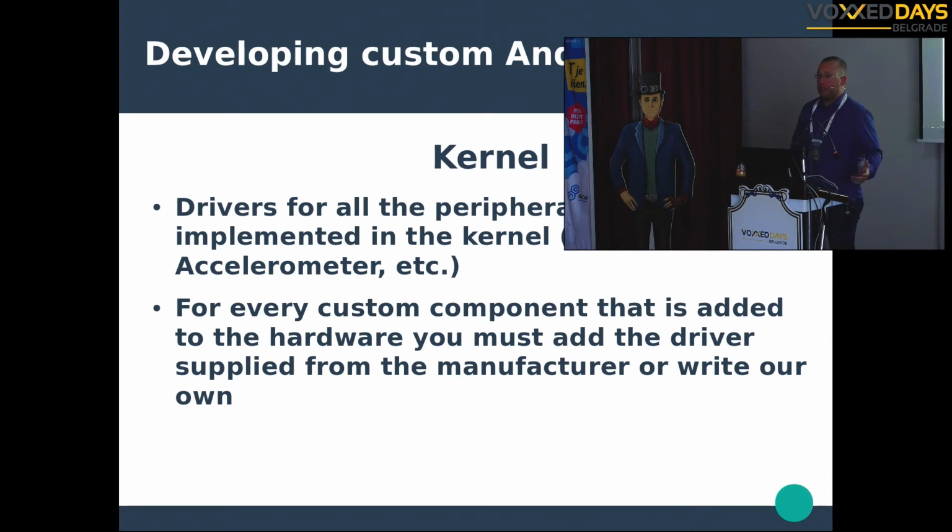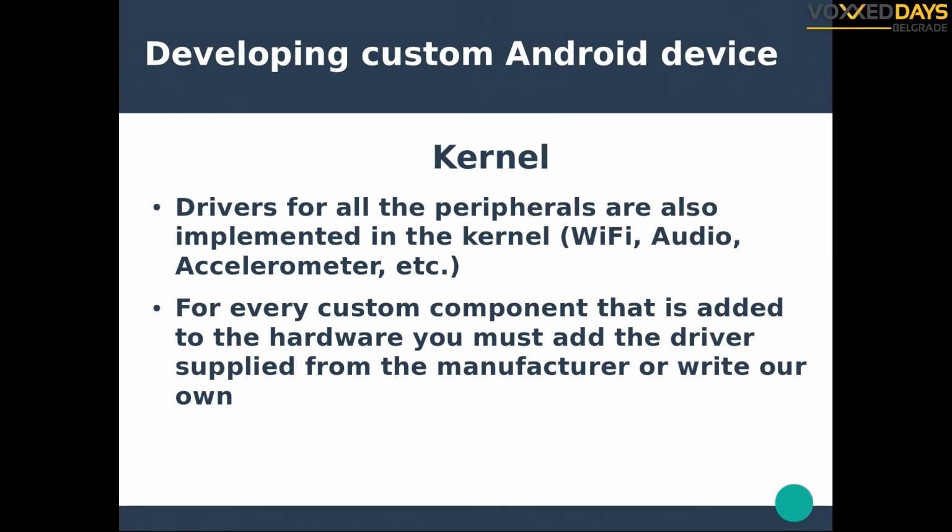And for all custom components that you have added on your device, you will have to either integrate into the kernel the driver that will be supplied by the manufacturer in some cases, and if you use something really custom and make it your own, then you will probably have to write your own driver. So you should consider that if this is a project or something, if you're not a Linux kernel developer, then you will probably need some guy or some team that will work on the kernel itself.